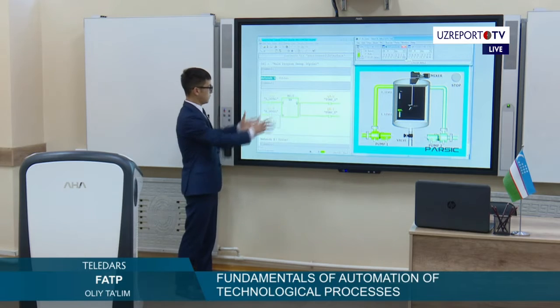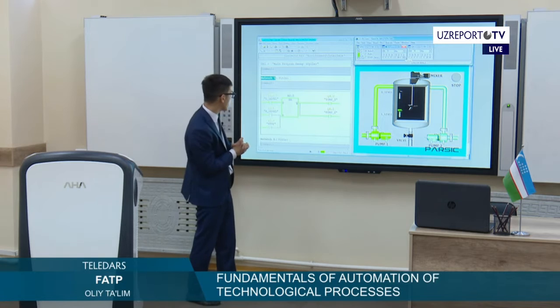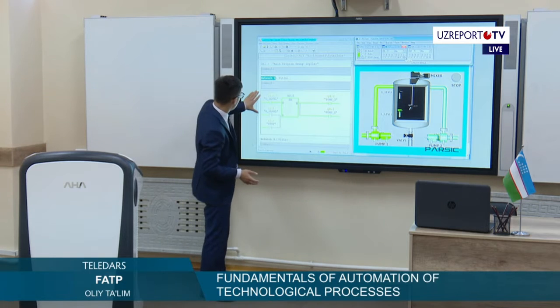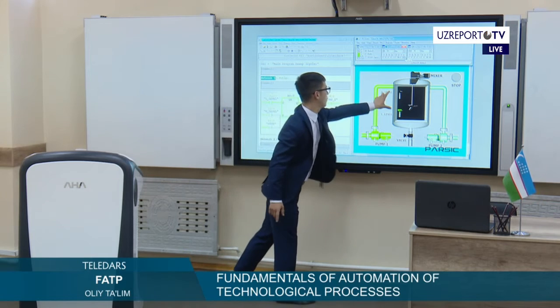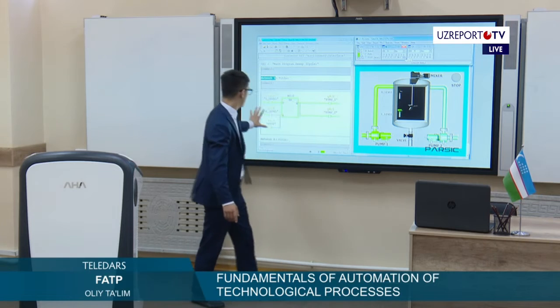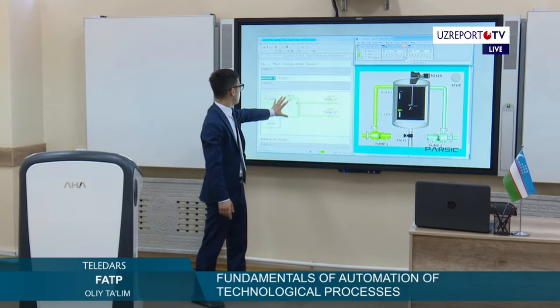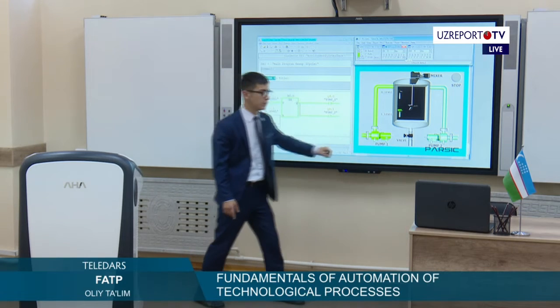And then here is a little model, the whole block where it works. First, we have high and low level inputs, and a stop push button. They come to set reset block number M0, and this command goes to pump number 1 and pump number 2.